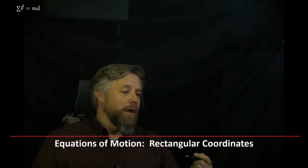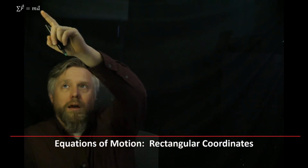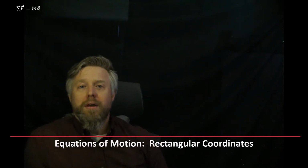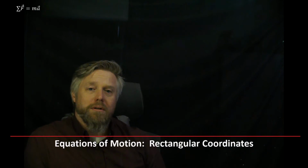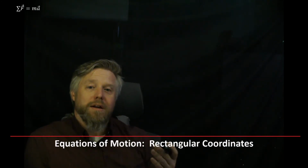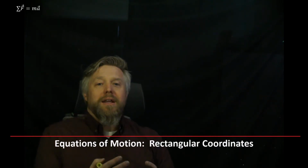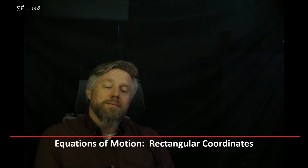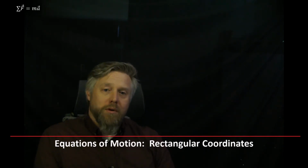So let's use Newton's second law and look at the equations of motion that we're going to use for kinetics. I have Newton's second law listed right up here, and you can see that I have some vector symbols on top because forces are directional, and so is acceleration. So really, it's the sum of all force vectors is equal to mass times the acceleration vector. We can use that in different coordinate systems that we choose to come up with multiple scalar equations of motion.